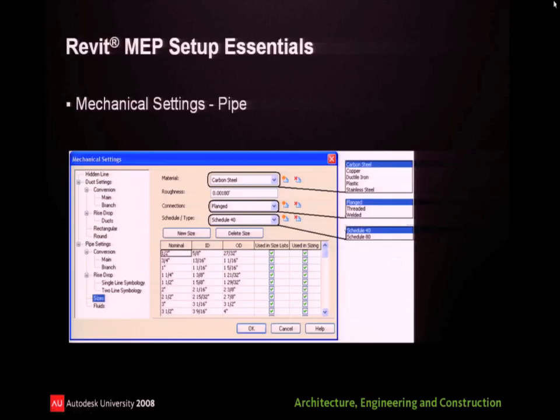But what this does give you a chance to do is, when somebody has a pipe they're putting on the drawing, you can limit it to what pipe size you want, or also for the ductwork, you can take duct sizes out that may not be applicable. For example, in here there's going to be 5-inch piping. We all know 5-inch piping is never available, but they do make it somewhere. So you can take it off the list. You can also set the material and so on. My company has not utilized this yet.